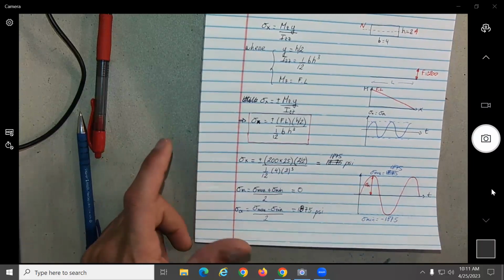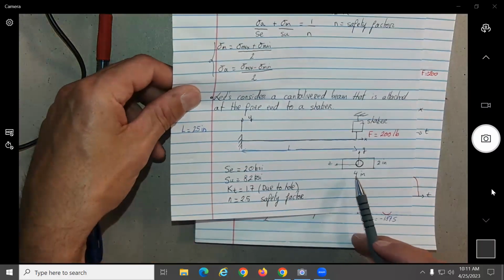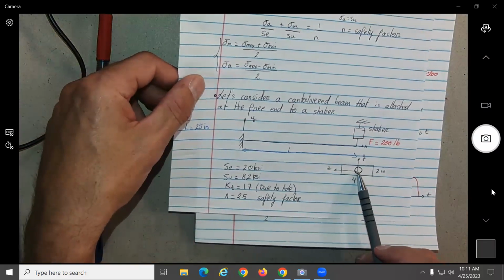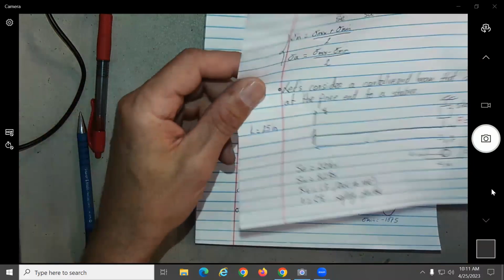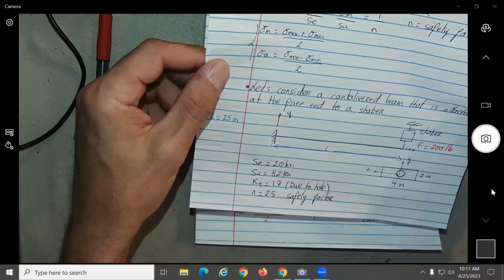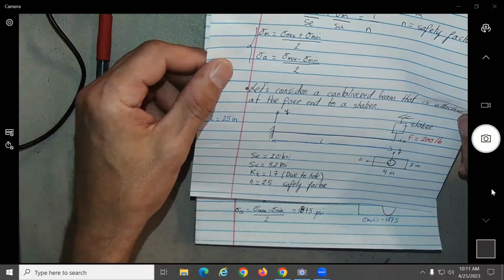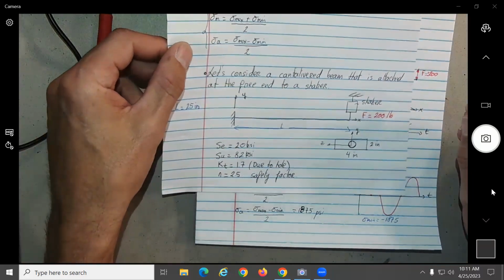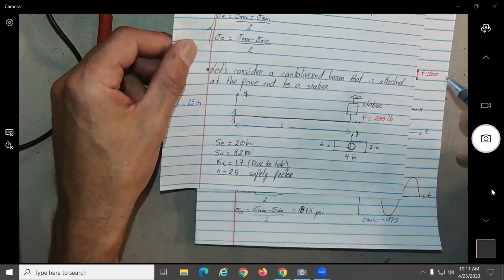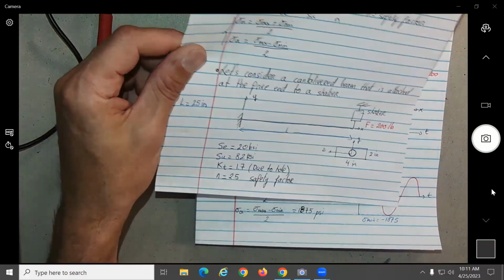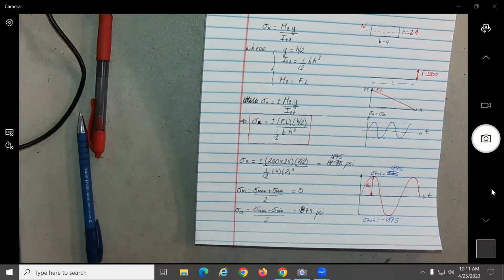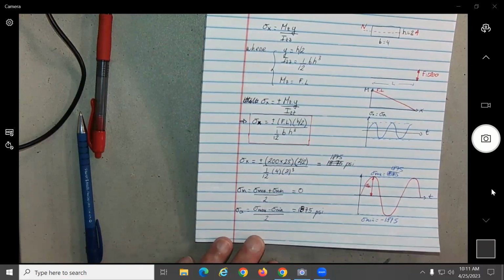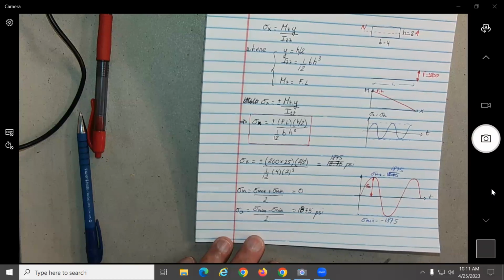So now, what is something we don't have to forget? What did you say was happening because of the hole? This hole is going to create a stress concentration, no? Negligible for the inertia now, like we're ignoring the area. Are we ignoring the area of the circle? Yes, we're ignoring it for the inertia. Depends how detailed you want to be, but if you want to do a first design, that's why we do it. This KT should take that into consideration.